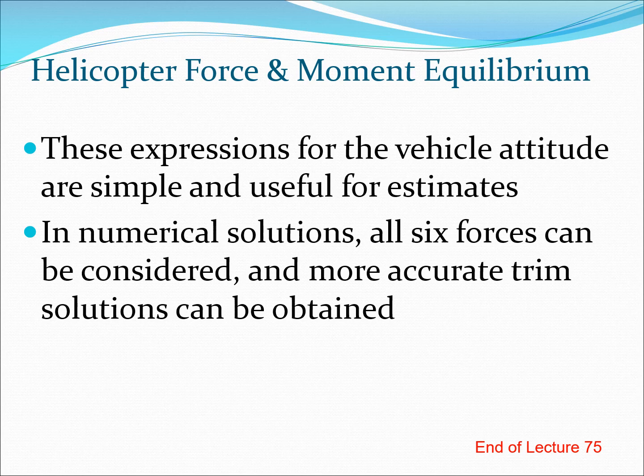Now, in numerical solution, all the six forces can be considered. The equations are more complex and more realistic, and you can essentially solve for the trim problem. So this is typically done using some Newton-Raphson method and so on, and you start with the estimate of the trim controls. This is typically obtained from rigid blade trim, and then you continue that process using the rigid blade trim starting values, and then the elastic blade is used, even the free wake model can be used, and you continue the Newton-Raphson procedure till you converge.